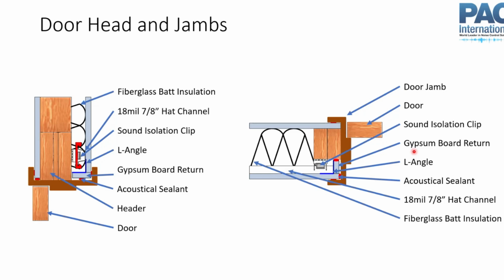So I guess the first thing to talk about here is if your door or your window is by far the weakest link in your wall, you might not really need much sound isolation on your wall. So think about that too. Let's make sure that if we're going to put a lot of time and effort and money into acoustical solutions, we're doing it in a way that makes sense. So if you've got a corridor door like in a hospital that's got a big undercut underneath it that you're not going to put a seal on, all that sound's going to go right through that. That's more than that 1-inch gap that we had in our STC 62 wall that took it down to an STC 41. So throwing a bunch of money at the wall is not really going to make it any better. Your submarine's still going to sink.